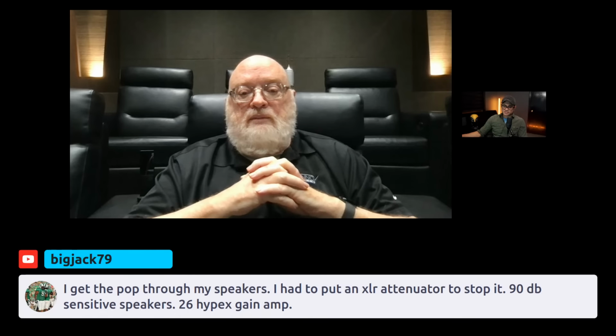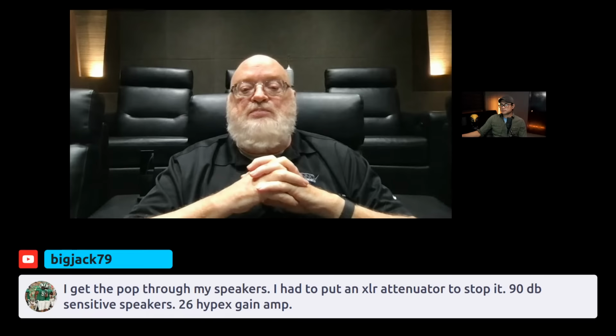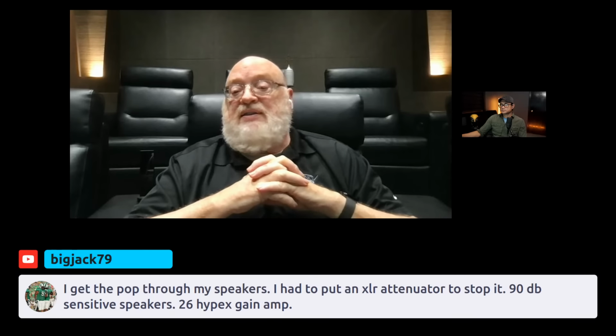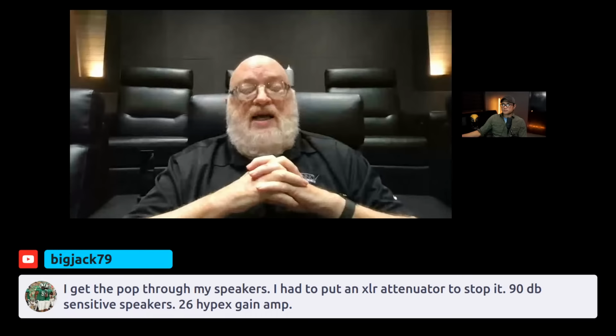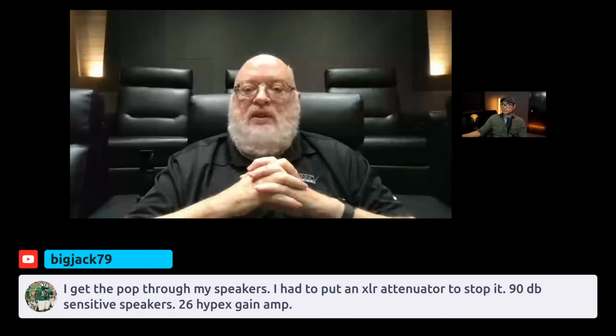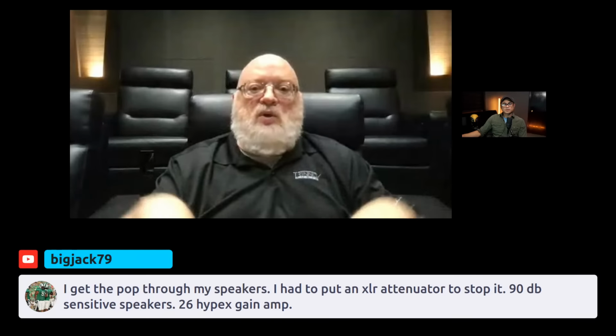Oh, it looks like Big Jack says I get the pop through my speakers. I had to put an XLR attenuator to stop it. 90 dB sensitive speakers, 26 dB gain amp. There you go. That's a lot more gain than you need in the power amp. And that's why the XLR attenuator worked, because it probably knocked it down by 10 dB. Our analog outputs are beefier than is typical in a consumer electronics product because we build everything to pro standards, because that's where we got our start in the business.